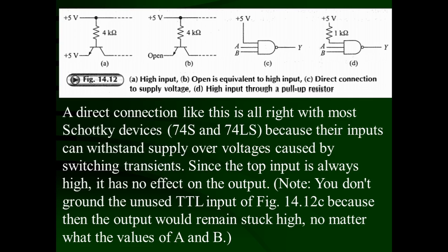So this unused input in case of the NAND gate should be connected to the high state only or power supply only.